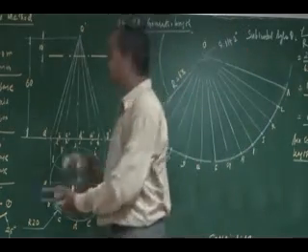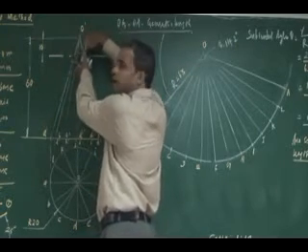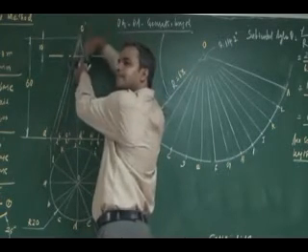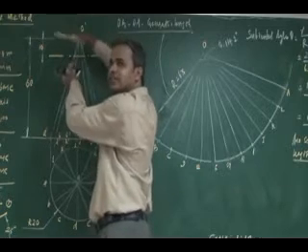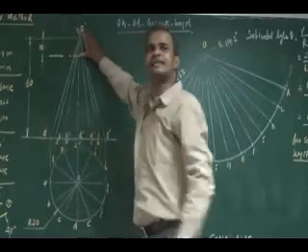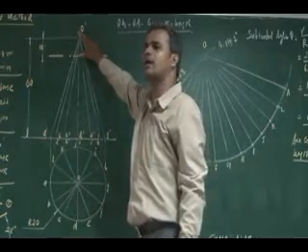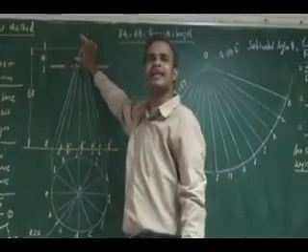So look at this top portion after cutting. The top portion alone, the removed portion after sectioning with a parallel cutting plane, is something like a smaller cone. To form this smaller cone, what is the radial length I have to measure?